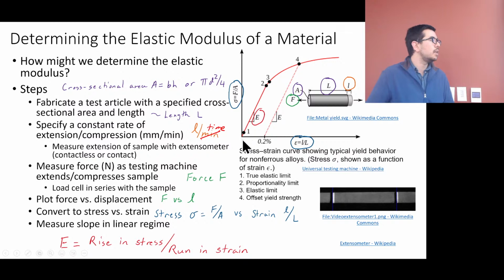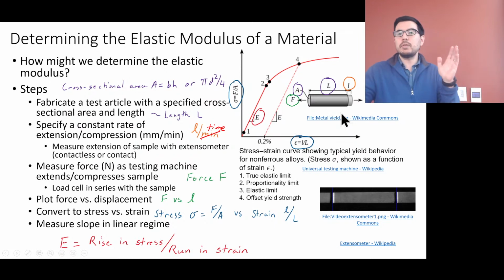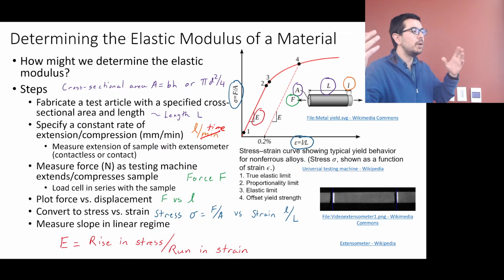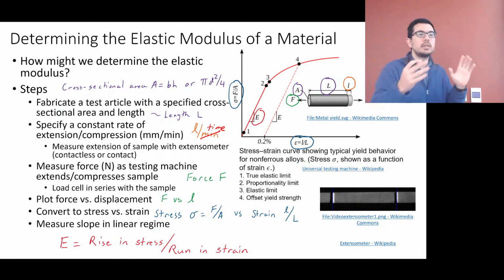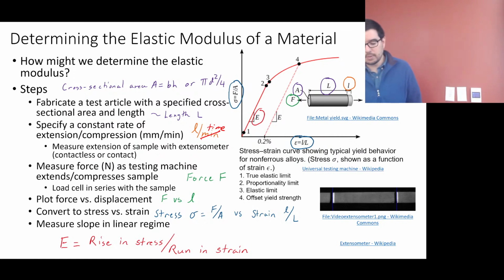Okay? But you'll see, for some of the rubbery materials, you don't just trust what's going on really low. They actually will tell you this is the elastic modulus at 10% strain, at a very high value, right? There's no way that a metal, I should say a solid bar, I mean, a metal can of course experience effective 10% strain if it's coiled into a spring, okay? But there's no way that a solid metal bar is going to experience that and not have yielded.